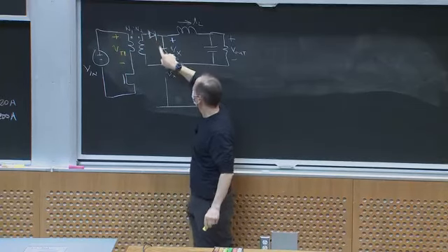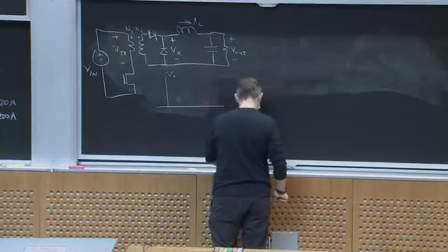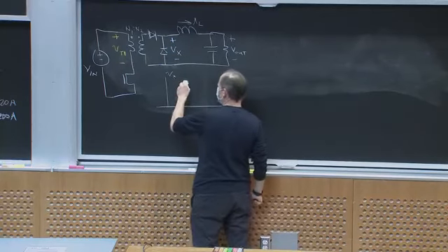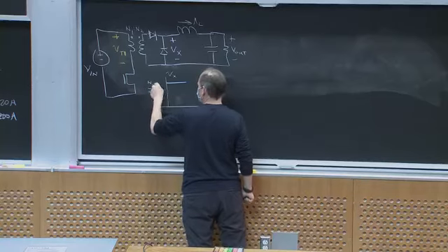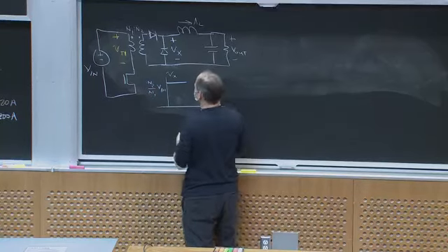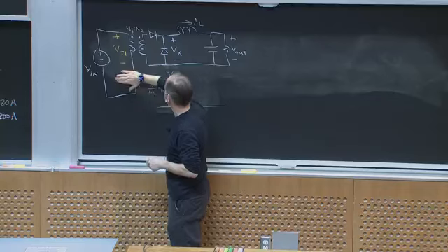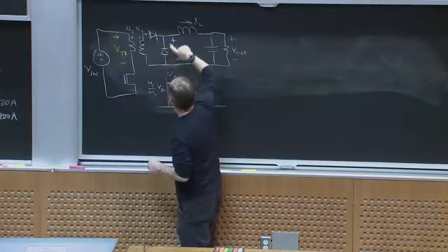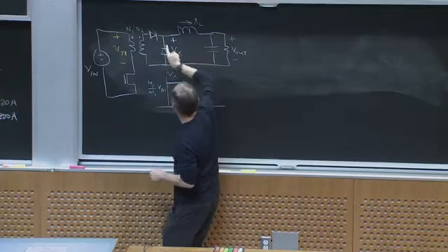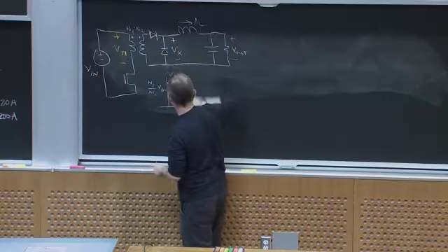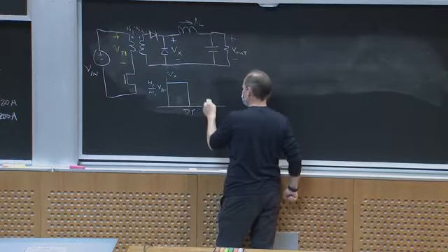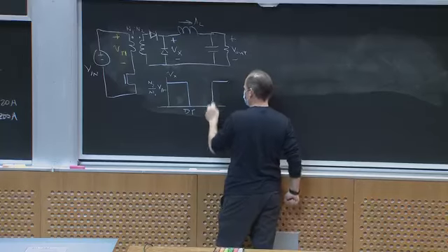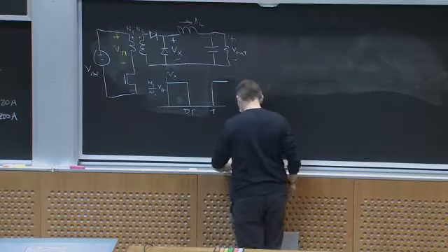This diode is going to be turned on, this diode is going to be turned off, so I'm going to get this voltage as being N2 over N1 Vn. And then when I turn this switch off, this diode is going to turn off, the load is going to carry through this diode, and Vx is going to go to 0. This is going to be dT, and that's going to last until T. And this is the voltage Vx, right?